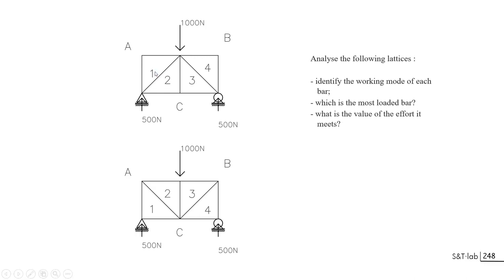You have to do this preliminary exercise for each truss. For this case here, we have just a vertical reaction on the right, and you have two bars connecting to this. If you have just a vertical force here, you cannot have a horizontal force here. So you can decide that this bar won't be active.